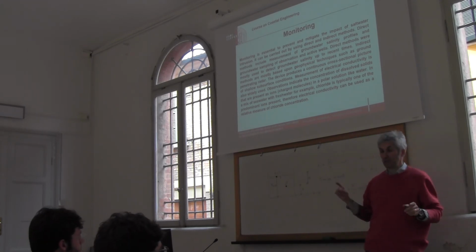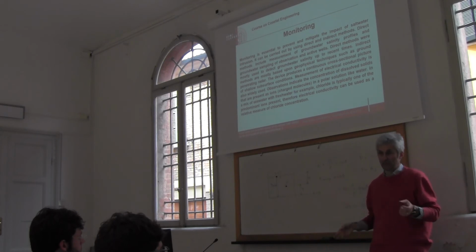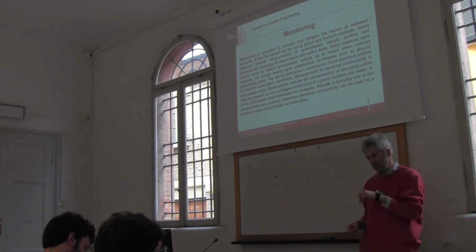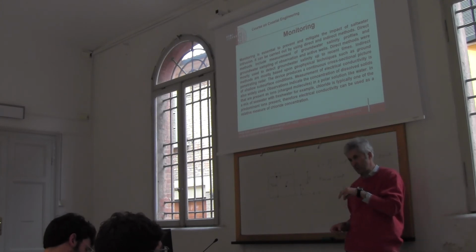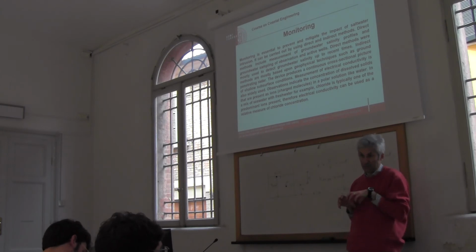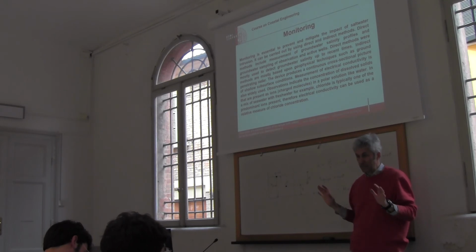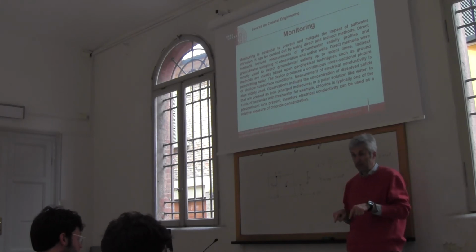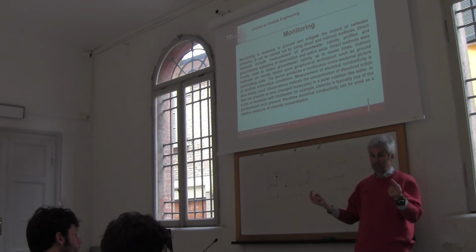Groundwater can be monitored also through piezometers. Piezometers are like small holes that are made in the ground, and from these small holes, typically we don't take water out, we just observe the water level. It is important because if we start pumping water from the underground, we need to monitor not only the well itself, but also other places, to see what the impact is on the groundwater level.